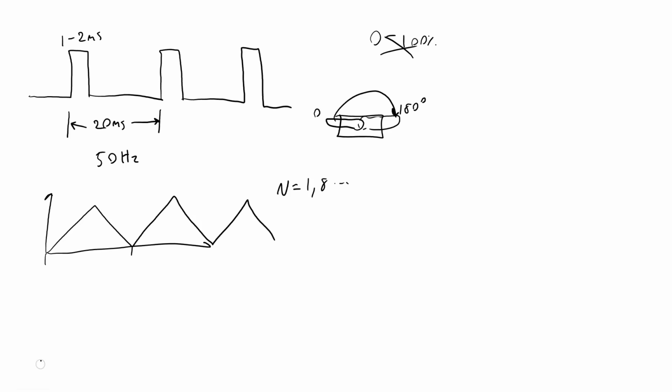And the way we're going to do that is to use another PWM mode available in the datasheet that is sort of similar to the clear timer on compare mode that we saw before, where instead of counting up to a default max value of 255, we are now going to be able to select the value that the timer will count up to, where instead of resetting, it will then count back down when it reaches that value.